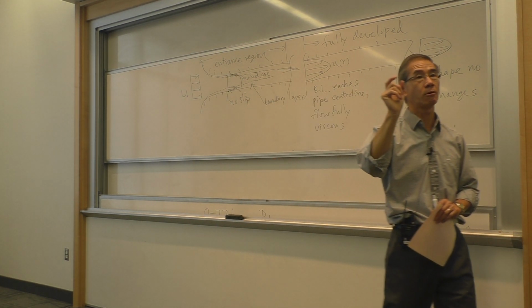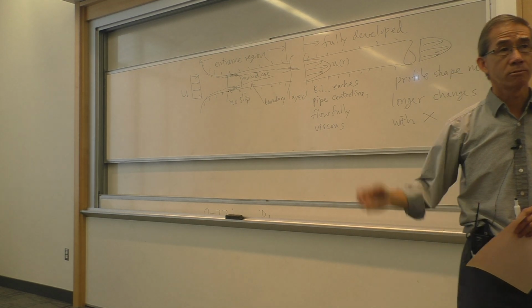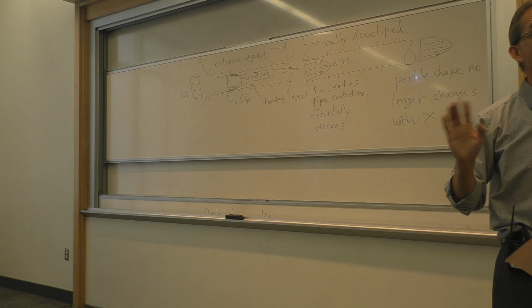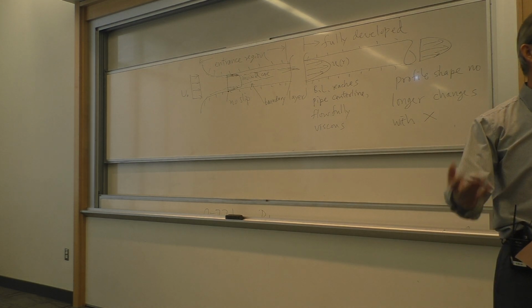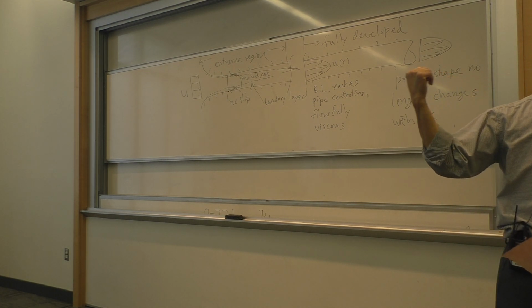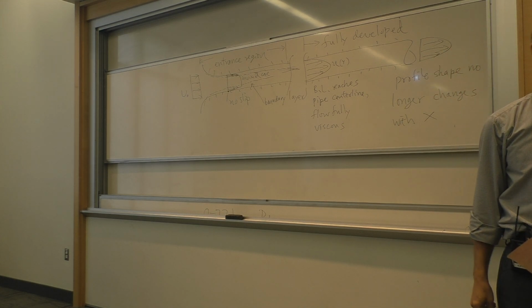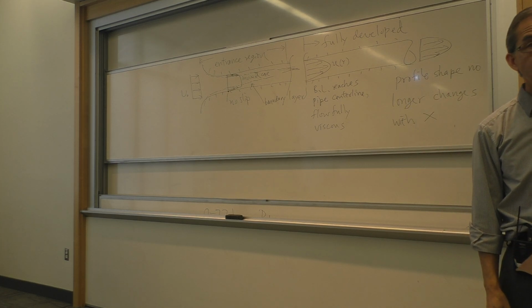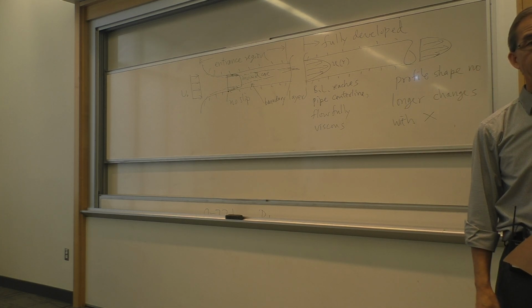It's actually a very small segment. And in most problems we deal with at this level, we don't even care about it. We'll always assume the flow is fully developed. But in real-life applications, this is the most important region. Case in point, the inlet for an aircraft engine. That's a pipe, but it's all entrance flow. It's never fully developed. And as an engineer, you have to account for that.